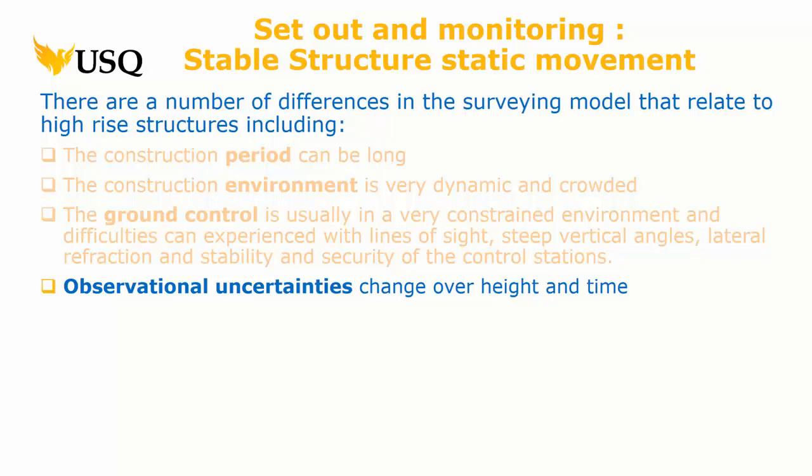Now, you need to understand this very clearly. If you go back to module 1, there's a section in there that actually contradicts most textbooks about errors in height. That's because most textbooks are related to set out and using theodolites and older-fashioned measuring equipment. So you have to consider that if you're using a total station and you're measuring heights, there is a different scenario, right? So make sure you understand that part of module 1 about vertical angles or zenith distances. It is a different approach.